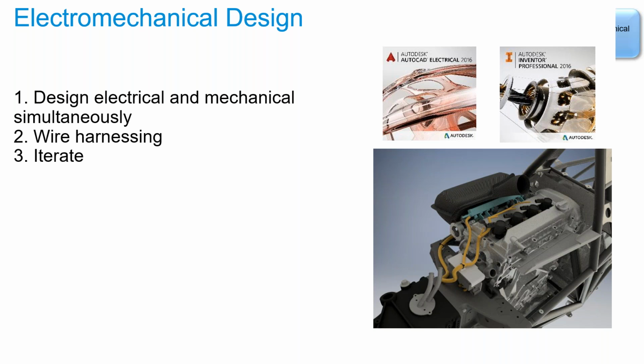You have to take care of a lot of things, like is it passing near a very hot element? Are there any very sensitive sensors? Or is space available for the wires to pass through different components or sub-assemblies? So this is very, very difficult to achieve. So what happens is you would never be able to get the actual length of the wire.